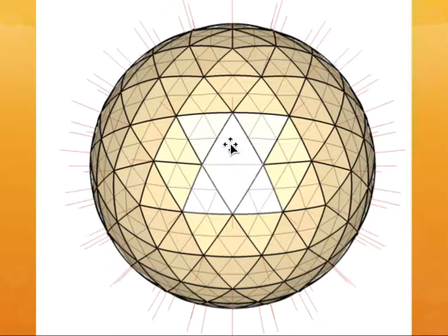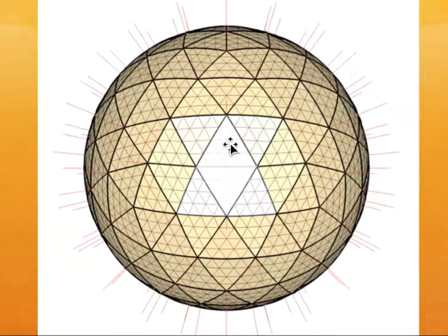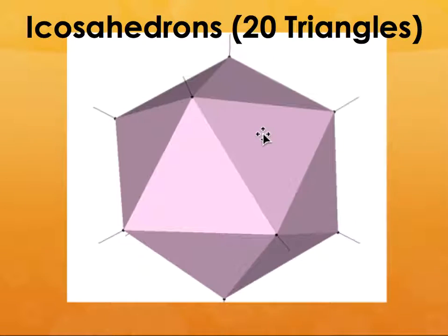So it's going to have some kind of facet type of build. If you want even more accurate parts, you have to increase the number of rectangles. It will increase the time to build it, but that's the only way to increase the accuracy of your parts.